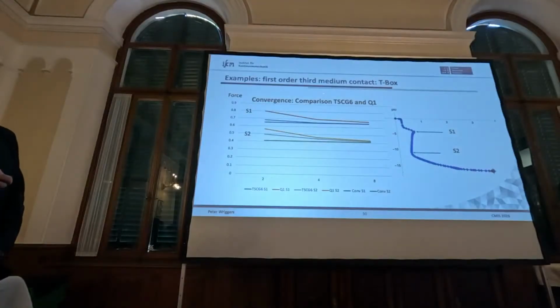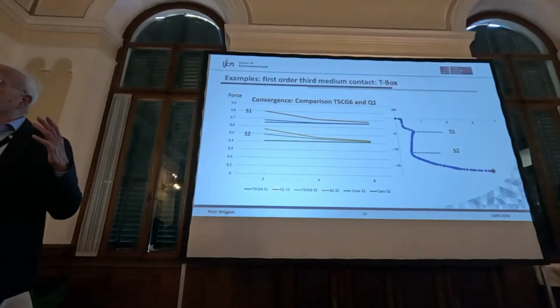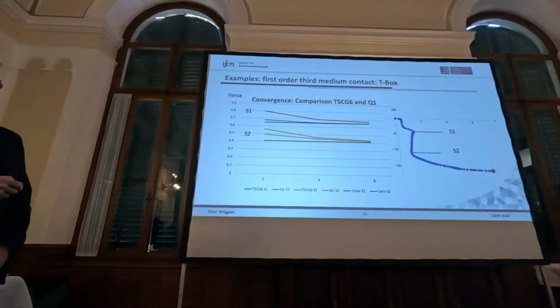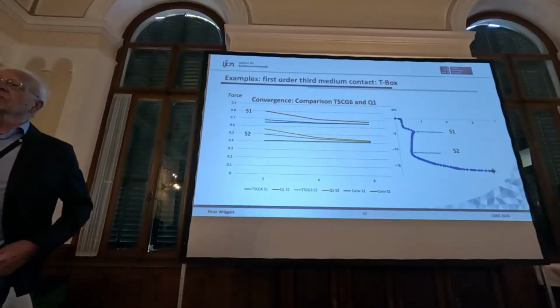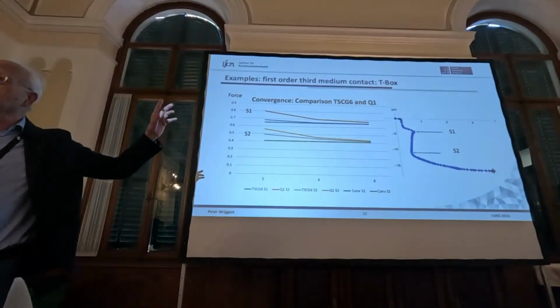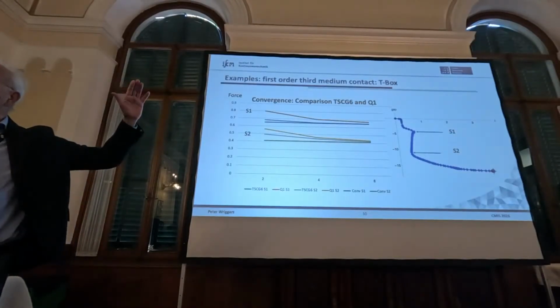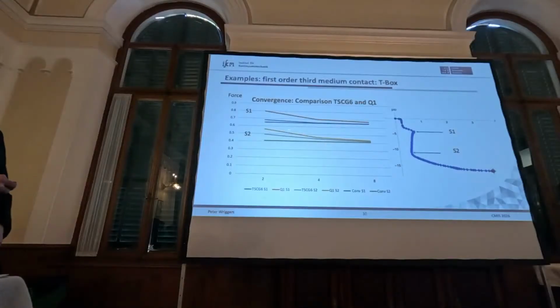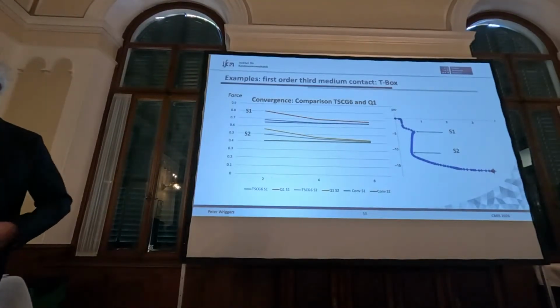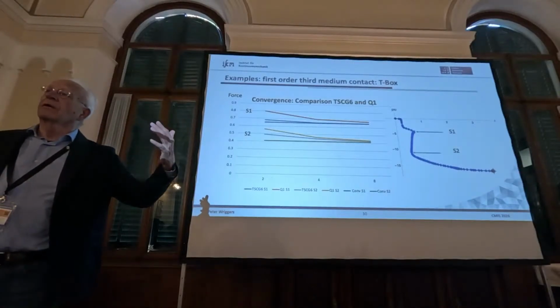The interesting part is here I compared some finite elements for the beam. If you take one which I did some time ago with Joshua Courage, which is sort of the best enhanced elements which you can have, it has no hourglassing under compression. And this one gives a different result. Here, this is the blue one, and here the gray one. This is sort of the converged solution, so it's very good. This is a Q1, which is sort of locking a little bit in this kind of application.